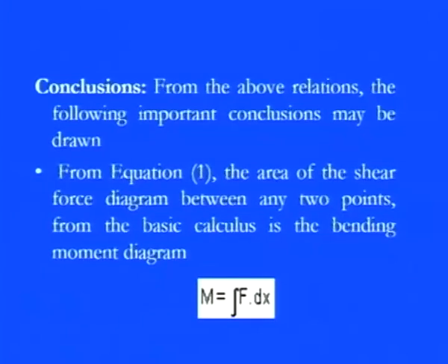It's pretty simple: if you know the force and the point of application of this force, you have the bending moment. So always keep in mind that if a beam is under various applications of load, a bending moment is always there, and it can be calculated by integrating the resultant shear force over the distance.